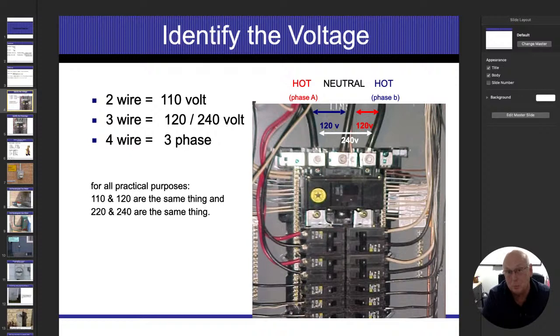There's going to be some situations, such as central air conditioning, heat, well pumps, electric radiant baseboard heat. Everything in those appliances is 240, because of which both phases are going to be equal. You're going to see that they don't even run a neutral wire to those items because we don't need it. We only need the neutral wire in case those two energized conductors are different.